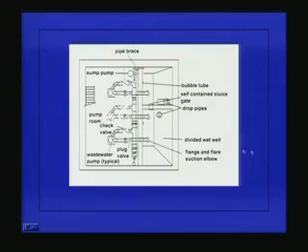We can also have an installation of this nature where we have 3 pumps operating in parallel. This is the wet well and this is the dry well. All the pumps are located in the dry well and the suction pipes from these pumps are going into the wet well, and delivery from the pumps is taken through a check valve and then put in the common header. All these delivery pipes are connected to a common header, and this check valve is provided to prevent the reverse flow when there is a stopping of the pump.